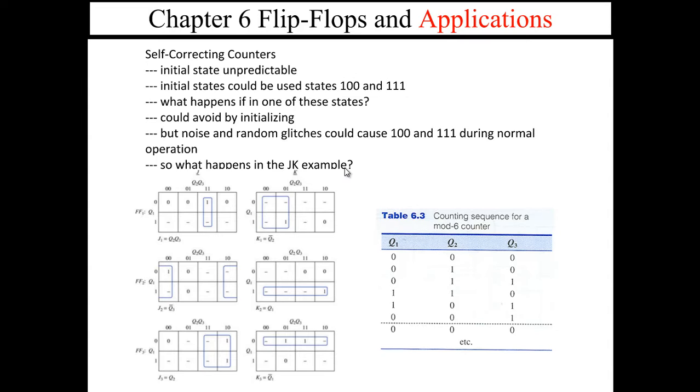And this particular torpedo, the engineers hadn't done this analysis to figure out what happens when these unused states are powered into, when the circuit powers on. And they didn't correct for it, and about 1 out of every 1,000 times, it would power on to the wrong state. And during testing, they never discovered this. The company that built the circuit did extensive testing. It was the Army's engineers that did more detailed testing, because they don't want to lose a sub, that found the problem. So let's call this the submarine problem.